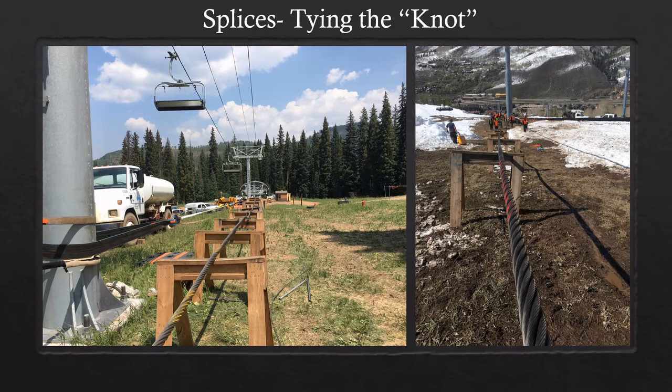This is a process that is carried out by some very skilled tradesmen, all completely by hand. I'll try to go over it here at a very entry-level view in this video. The first step is to detension the rope and lower it down from the towers onto wooden pedestals called sawhorses so the work team can work easier.